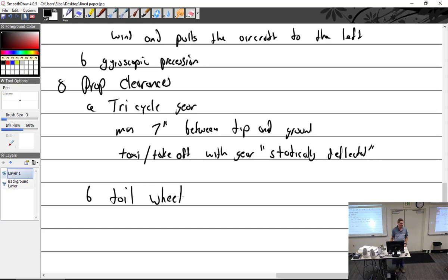Because I could overinflate the front tires, wouldn't get a little bit additional clearance, or put larger tires on the front, get some additional clearance on a tail dragger, right? Well, you can go more. This is just a minimum of 7. Okay. They don't want you to. It's no more than 7. No, it's a minimum of 7. So tail wheel, minimum of 9.